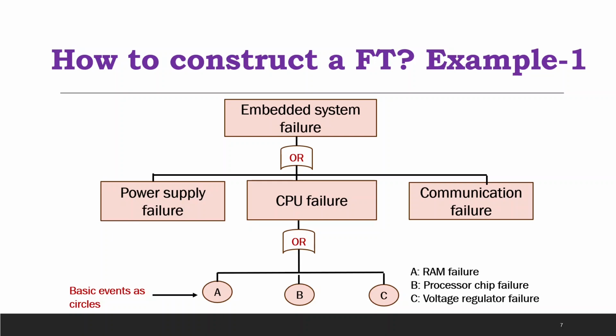But when we do the board level FTA, we can go down into the chips and identify which chips could be the issue. And if we want to do chip level FTA, for example, if we want to do the fault tree analysis of a RAM, then we would have to go into the silicon level or the solder joint level and so on, depending upon the context.